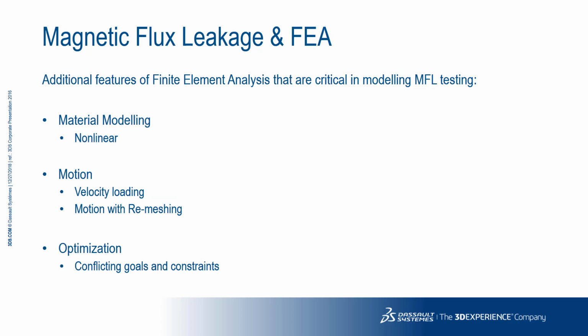Let's now take a look at some of the features of finite element analysis which are crucial in successful, efficient use for solving MFL simulations. Because the method relies on inducing a high magnetic flux density in the pipe, accurate nonlinear material modeling is a must. High-speed, non-destructive inspection systems using the MFL method are in great demand for online inspection and defect characterization, especially in pipeline maintenance.